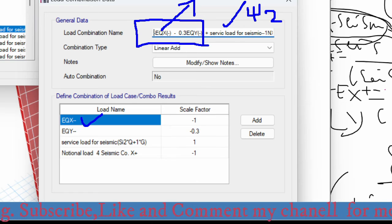Sorry, this is minus 1, because we are applying in negative x direction. So here we have minus 1. So 100% of the seismic load is applied in negative x direction, and also 30% of the seismic load is applied in negative y direction. So here the governing direction is negative x direction. So that is why we are taking EQ negative,